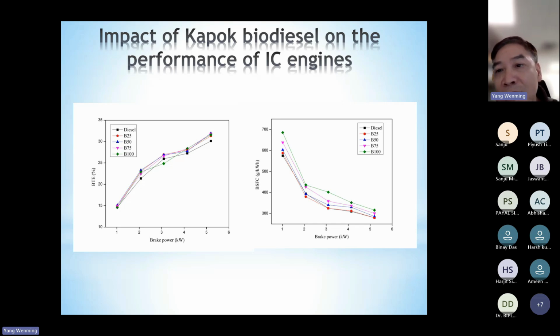So this oxygen brings down the heating value. Since the heating value is smaller compared with the diesel fuel, the fuel consumption will be higher to produce the same power, correct? So this one is reasonable.